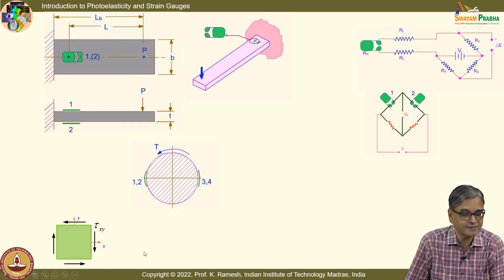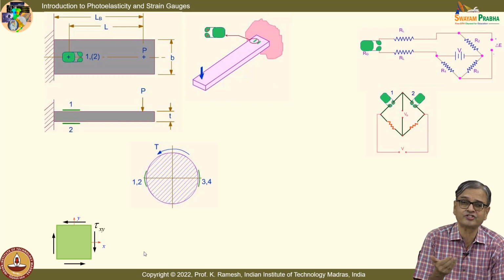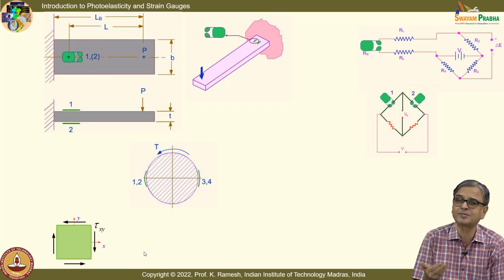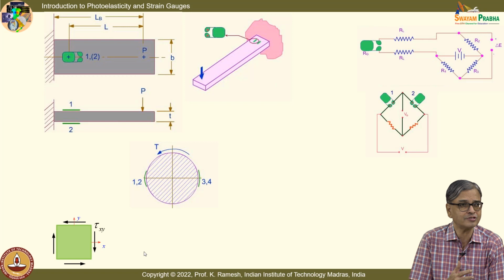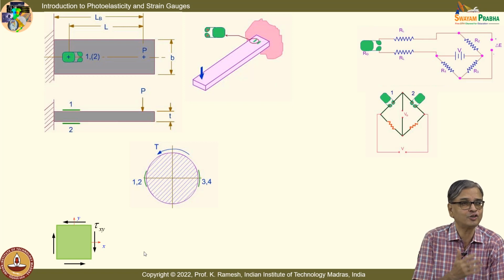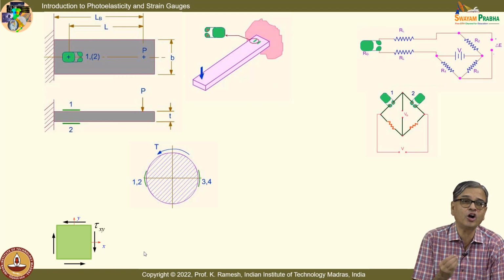This is what I am looking at, which you can visualize. Once you have drawn this, you have already studied the Mohr circle, and we are dealing with an isotropic material. In an isotropic material, the stress state and strain state are identical. Your principal stress direction will coincide with the principal strain direction. With that knowledge, can you visualize this as a combination of axial strains? A pure shear stress state is introduced. Can you go to the Mohr circle? Draw the Mohr circle for this and find out at what angle you have the principal stresses.